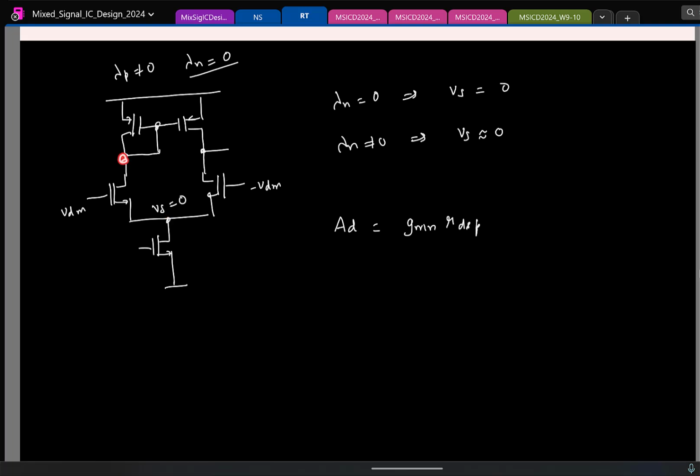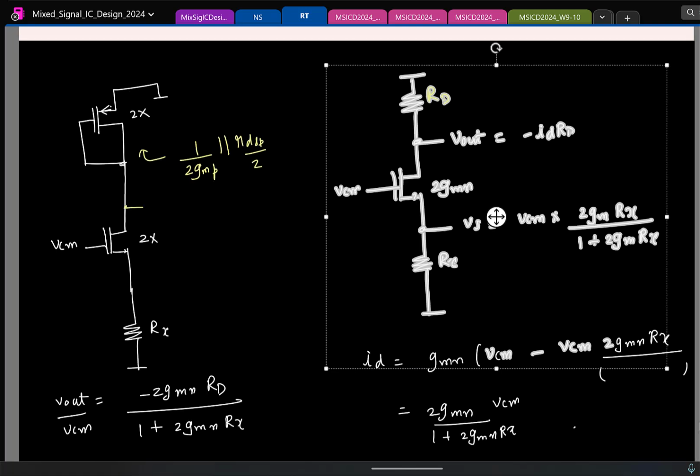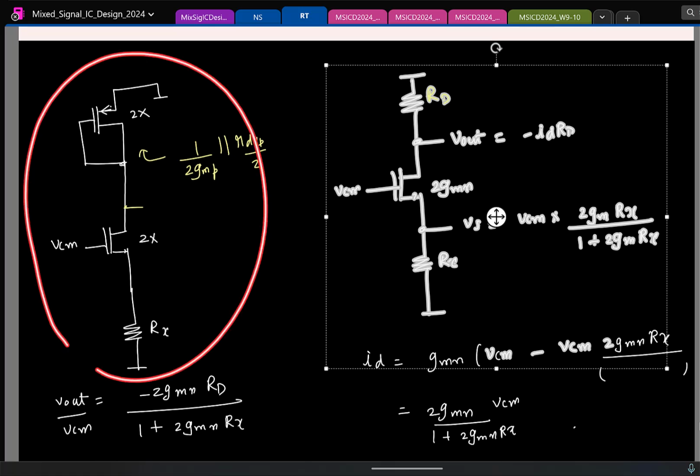That is because these two voltages will not affect here, so this looks like a symmetric circuit. And the second thing is, if I look at a common mode case, that is, if the excitation given to the two sides is the same, it is a common mode input, then the overall circuit looks purely symmetrical. And in that case, you can reduce it like this.